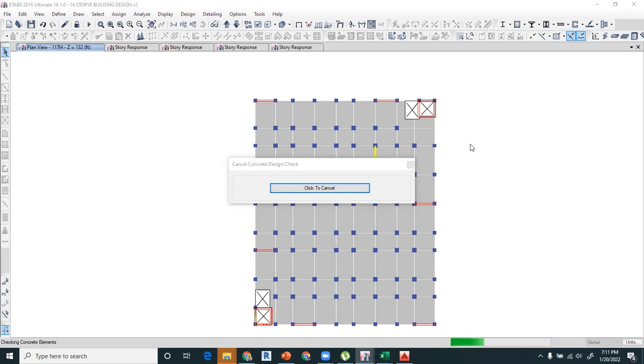If I design only gravity load, what checks should I need to do? What kind of check can I do if I only consider gravity load? So these checks are for the seismic design of the building. There is no such check for the gravity loads. For the gravity loads, there are only checks for serviceability, that's deflections, which we were doing in our last session. So you have to check the deflection. If it is within the limit, then you will go for it.